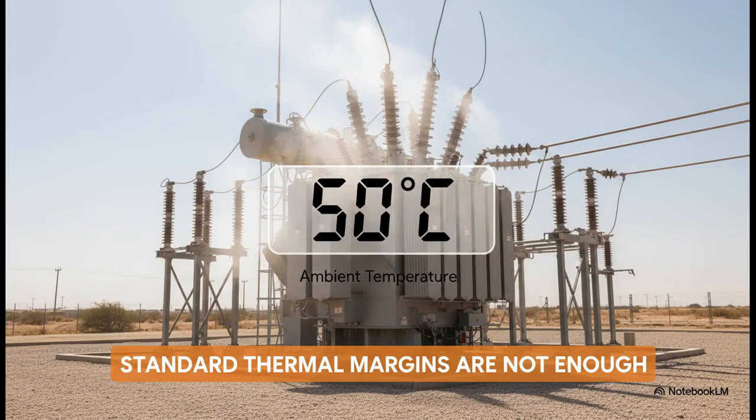And this is where things get really interesting. Because the local climate has a massive impact. You're not designing for a cool climate here. You have to size your transformers to survive a constant ambient temperature of 50 degrees Celsius. Your standard off-the-shelf thermal margins, they just won't cut it.